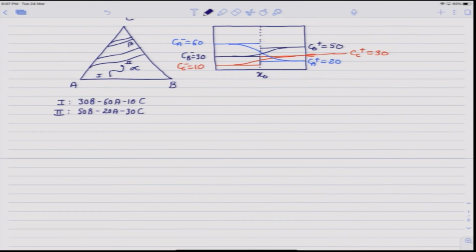However, if we form a diffusion couple between, let us say, alloy alpha 1 and beta 1 here. So, to start with, the two terminal alloys have different compositions in the diffusion zone, or there may be a planar interface between alpha and beta. So, again, for mass balance, the diffusion path has to cross the straight line joining the two alloys at least once. So, this diffusion path may look something like this. The way the diffusion path passes through the two phase region, the diffusion structure may be different. There are certain rules that help us to correlate the diffusion structure that is developed in the diffusion zone of an isothermal ternary diffusion couple with the features of the ternary isotherm. So, let us look at those.